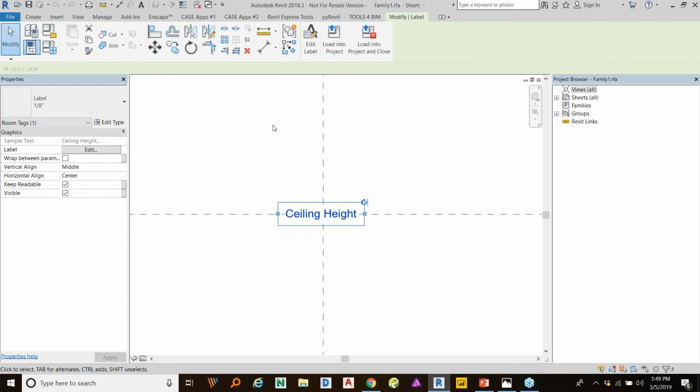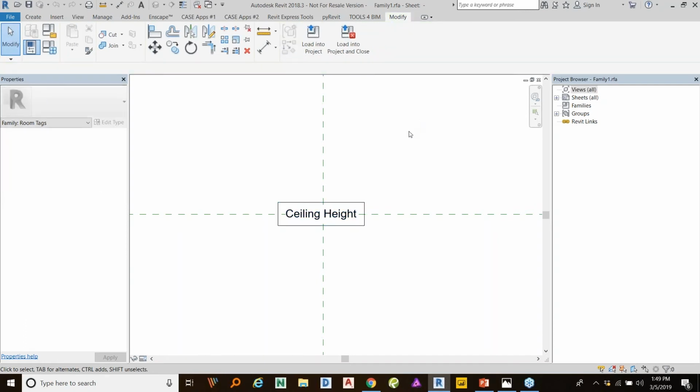So once you've got that, you can do that for pretty much all of your tags, and you can automate them through your shared parameters. It's a really nice way to think about it. And then if you really wanted to self-automate, which I'm not going to talk about because that's a whole other topic, you would create a global parameter where the project knows that the shared parameter is being associated with it and automatically knows to tag it that way.